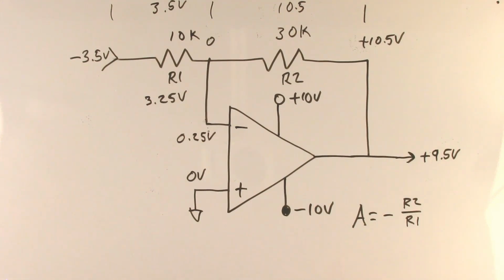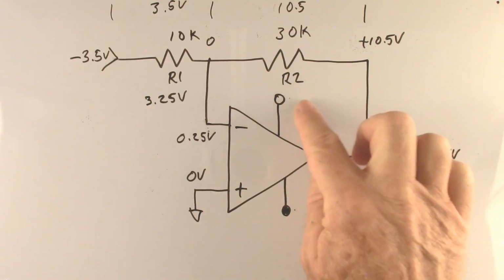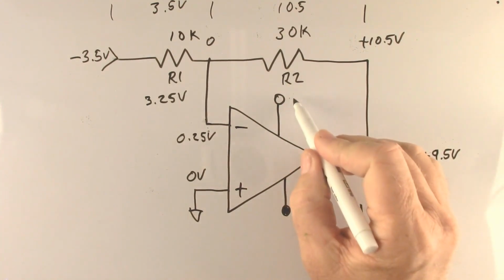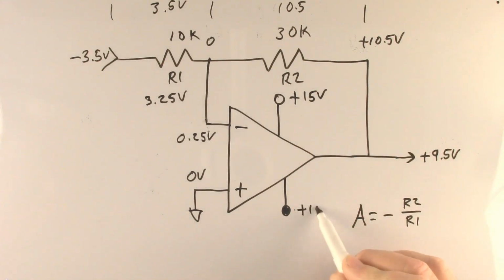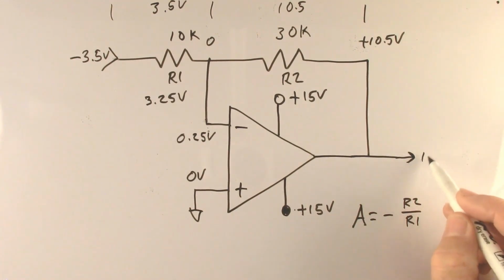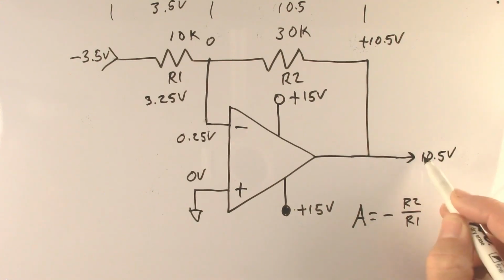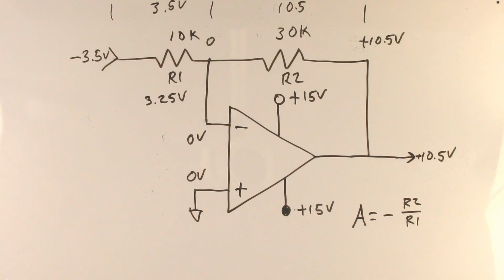And last but not least, and sometimes the more logical thing to do, is simply increase the supply voltage. Slight redesign of the circuit. Now this can reach 10.5 volts. This will balance out to 0 volts, and we will have a properly working inverting amplifier. In our next video, we'll take a look at the next step, which is the differential amplifier.